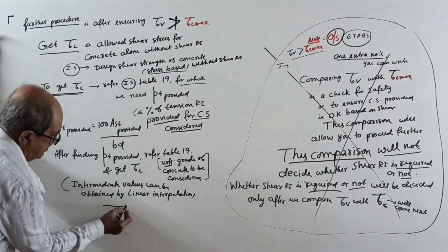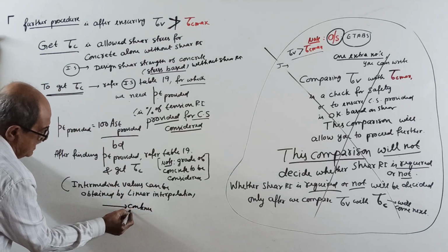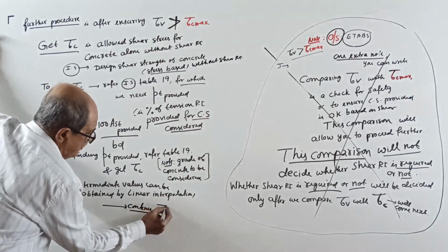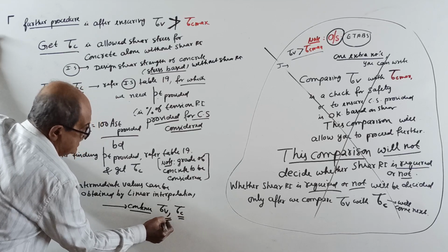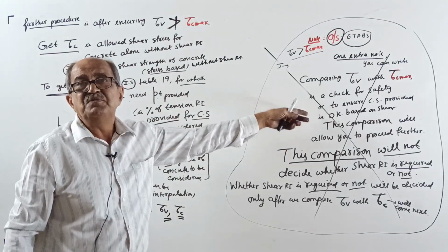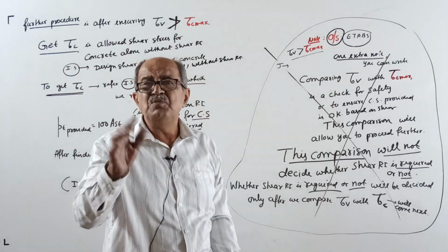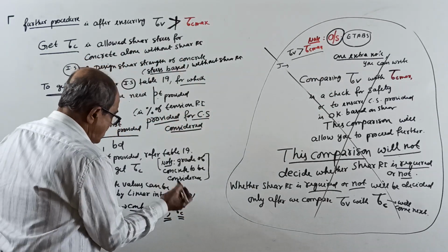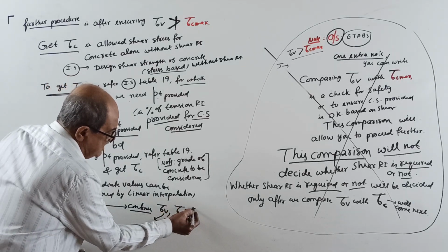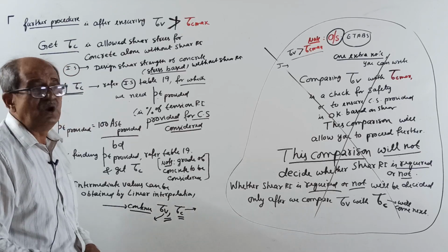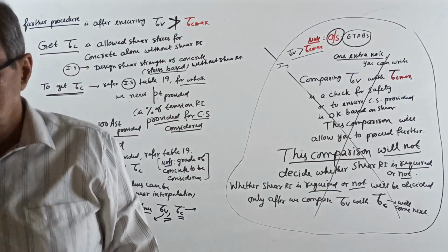Now, I will continue the procedure. Make a note now. When I continue the procedure, you know the value of tau v and also the value of tau c. Tau c maximum will vanish once it is safe. Okay, now you already know how much shear stress is to be resisted and how much shear stress concrete alone can resist. Both are over.